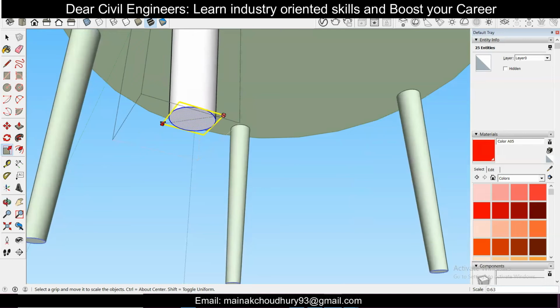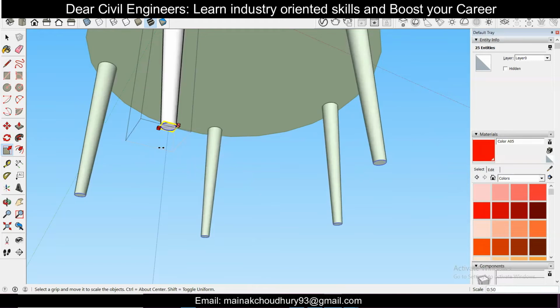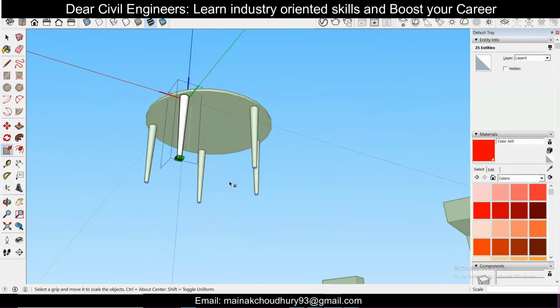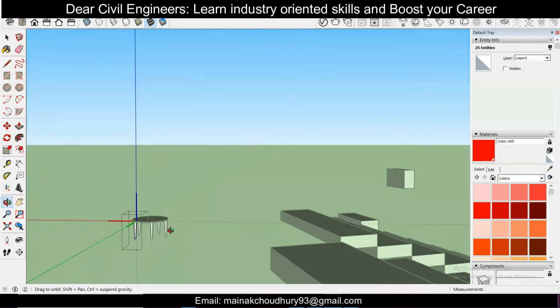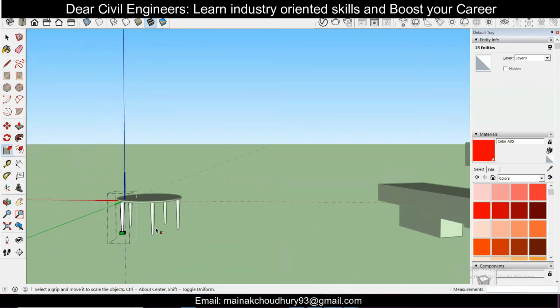You can see that the design has been tapered at a particular side, if you are viewing this from the right side of the computer screen. But if you press Control, then it will be tapered from the center. So we want that. Just press Control and then press Enter, and you get a well designed tapered, round table legs. So like this, you can play around and make use of these groups and components.